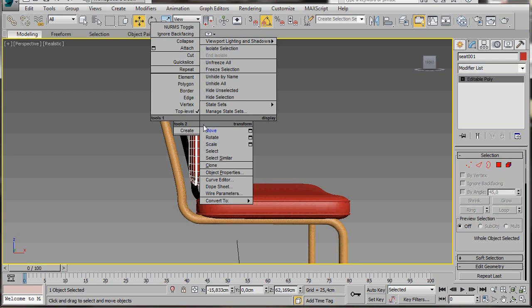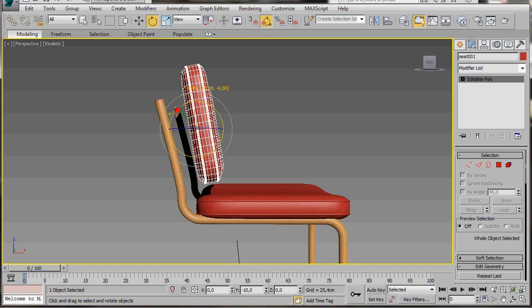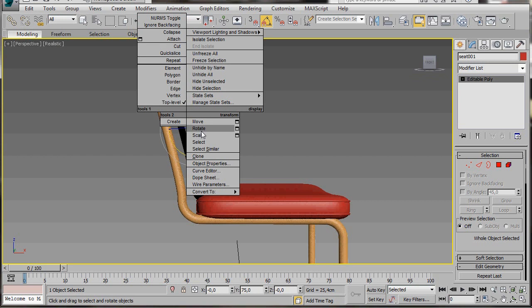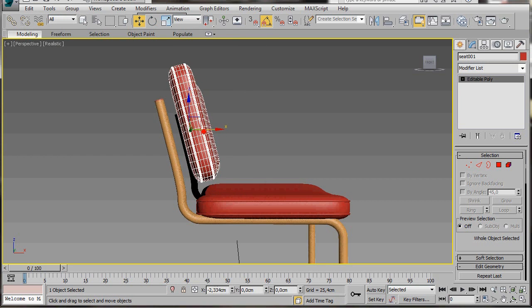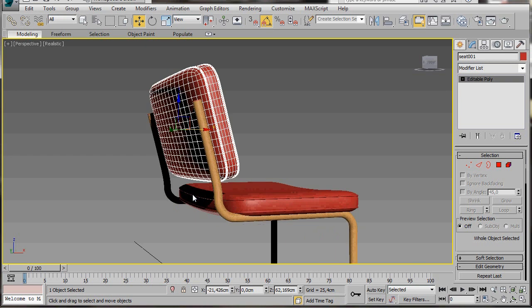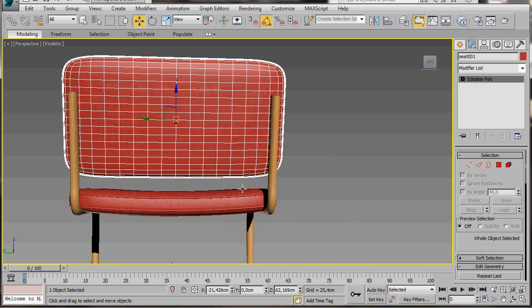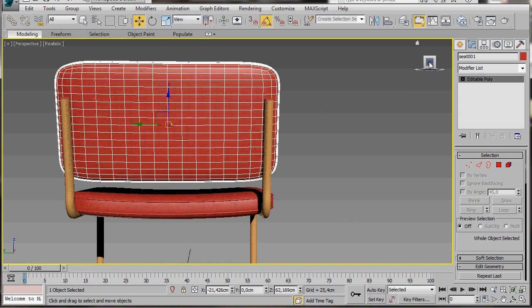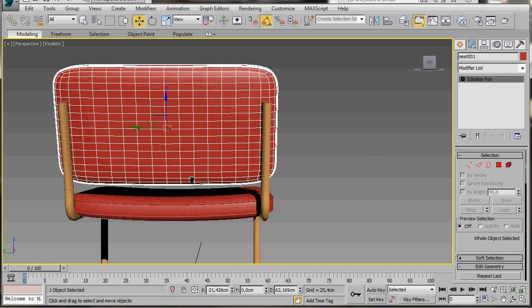I'm going to rotate it now. I'll leave my angle snap toggle on, it's easier to rotate, and just move it in. There we are, I'll orbit around. I'll pop back up to the view cube again, and I'll just click on left. That'll straighten everything for me.